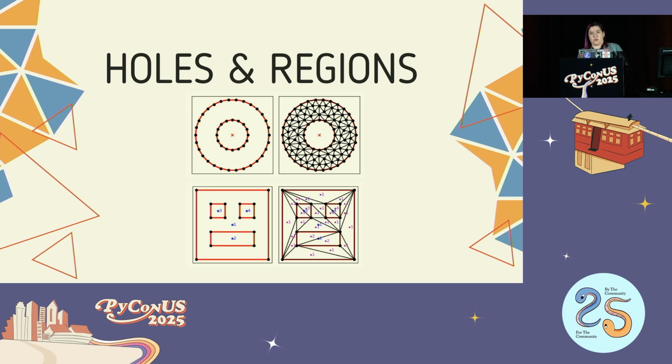The way that Triangle defines a hole is you need to have a closed polygon, and then you put a point within that to specify that it's a hole. Regions allow you to specify a finer mesh in certain areas, so it's just another way of specifying different pieces of your discretization.